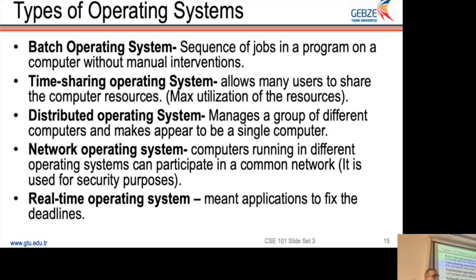If you go below 1,000 computations per second, it feels like vibrating. It doesn't feel smooth in operation. So 1 kilohertz, 1,000 computations per second, and repositioning the motors is required. So you shouldn't be slower than that.